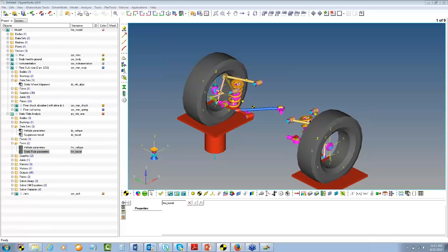Also for the tires, it is going to make many things bad. In that condition, it is desirable to put some kind of mechanical stop, and it is a hard rubber that you put in there, and they restrict the movement of the wheel above a particular value. And generally that value should not be hit. But there have been a few cases where I have seen that, although it is desirable, I have not seen that much with Baja cars.